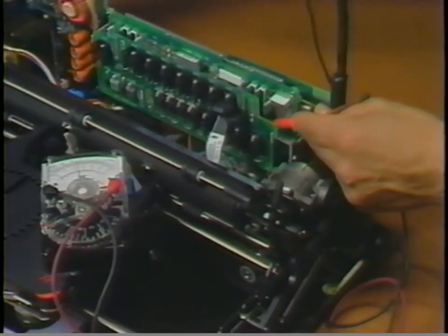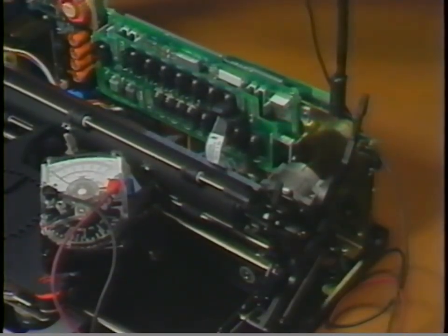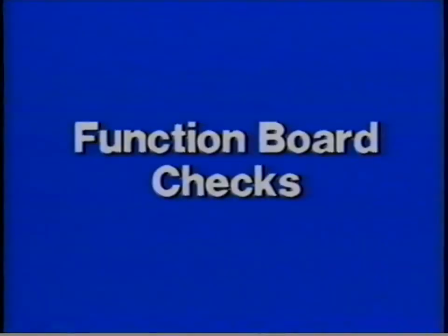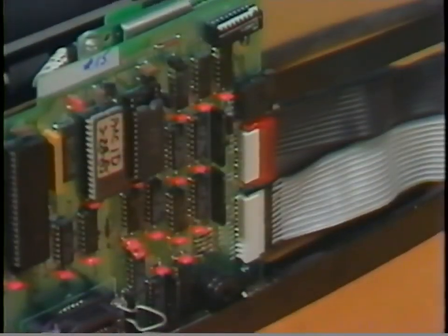Turn the machine off and reinstall the transport motor plug. Next, we will look at the diagnostic check for the function board. First, we will locate the function board connectors.